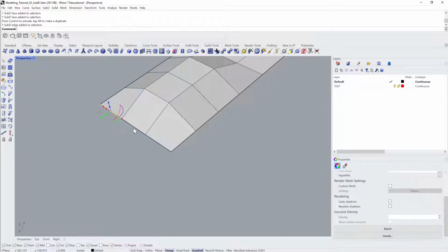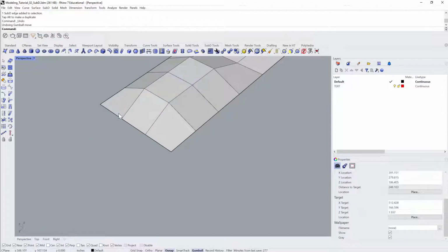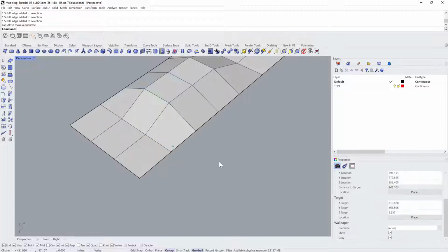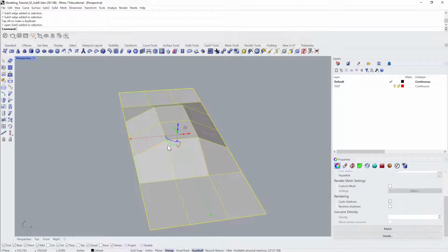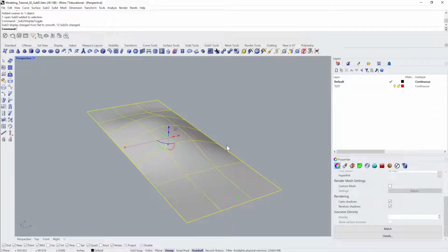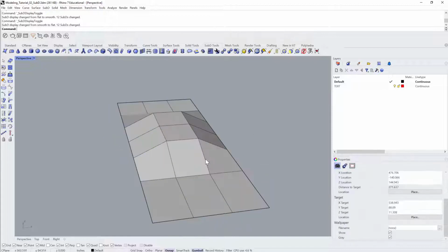And I'm going to pick those vertices, and oops, I don't want to move them. I want to extrude them, so do that. All right. Okay, so now tab, I'm getting something like that. Let me crease these corners. So I'm going to crease those corners, then I'm going to hit tab. Now I'm getting sharp around the edges.